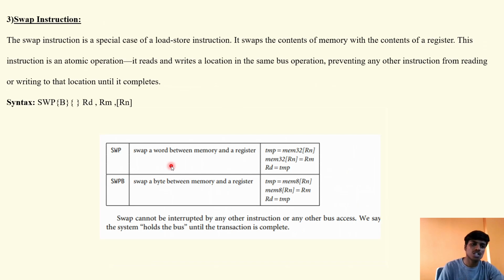So this instruction is an atomic operation. It reads and writes a location in the same bus operation, preventing any other instructions from reading or writing to that location until it completes.